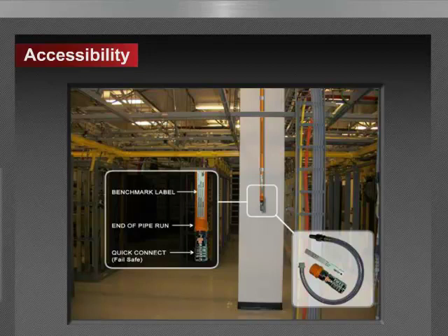Well, generally, what might drive you to that is codes and standards requirements. But generally, if you have combustibles in the raised floor, or in the event that you have suppression, say gaseous suppression or pre-action systems below the raised floor, think in terms of the requirement for needing detection to actuate those systems. So it comes down largely to the presence of combustibles and the need to initiate suppression systems that may be located below the raised floor. Okay.